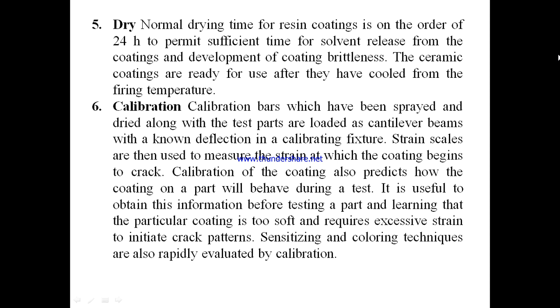Then the normal drying time for resin coatings is of the order of 24 hours, to permit sufficient time for solvent release from the coating and development of the coating material. The ceramic coatings are ready for use after they have cooled from the firing temperature.